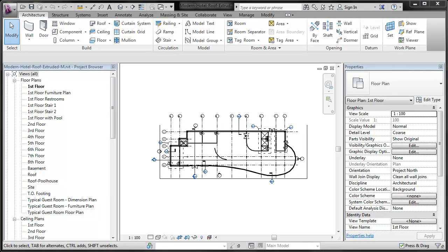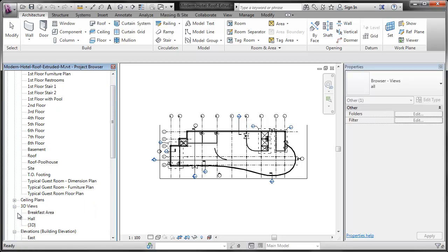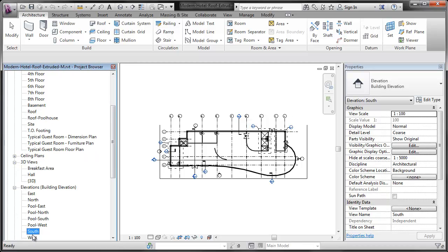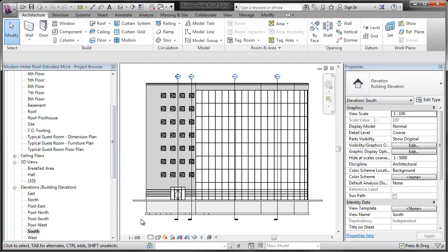Okay, in this video we're going to do practice 11b, which is creating roofs by extrusion. So in task number 1 we're going to create a roof by extrusion, so we're going to open up a new Revit project, and what we want to then do is go to the south building elevation view. So we're going to scroll down here, let's turn off ceilings, then go to the south elevation. Double click that.